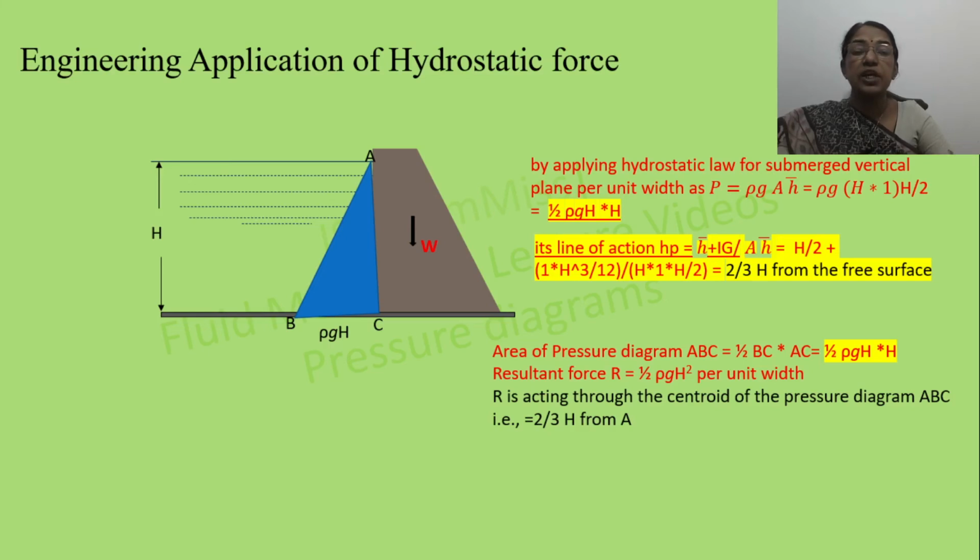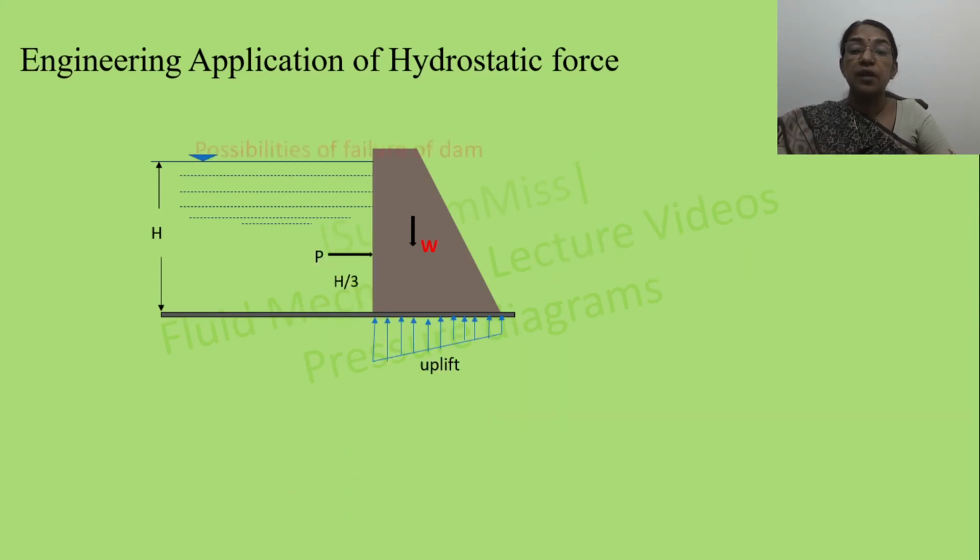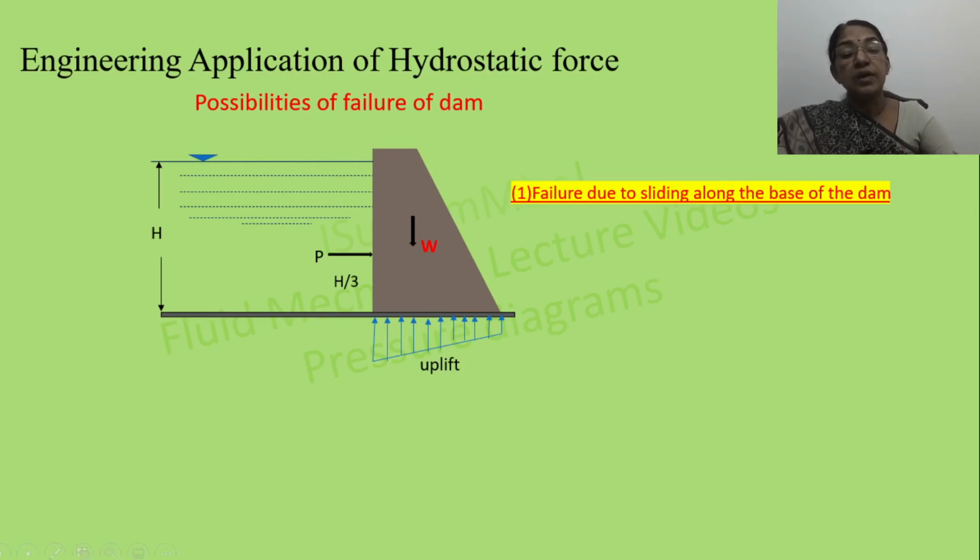Some of the common questions usually asked in competitive exams are regarding the stability of the dam. There are 4 points to be considered regarding the stability of the dam. In addition to the pressure forces and the weight of the dam, we have to consider the uplift force also. What is uplift force? It is an active force within both the foundation and the concrete structure itself. The pressure exists in cracks, pores and joints of the concrete and at the interface of the dam structure and the foundation, etc.